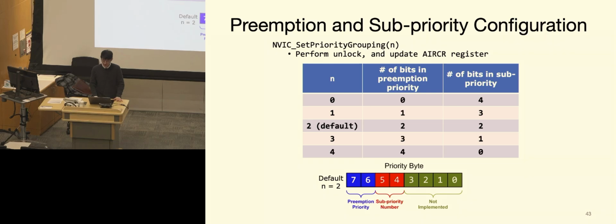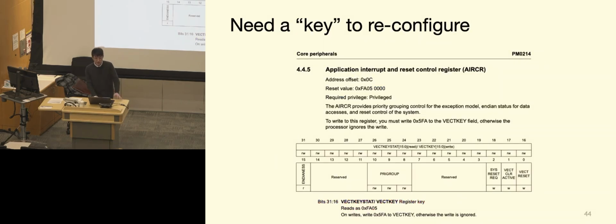Because these things, as you can probably imagine, are quite important. If you set the bits distribution to 2 bits, and then change to say 3 bits, 1 bit, those things are going to change the program or the whole processor behavior quite dramatically if there's an interrupt happening.